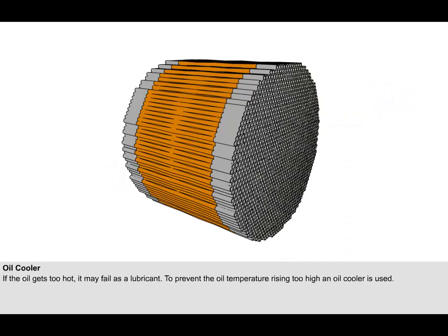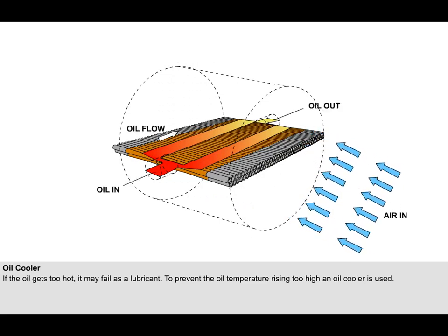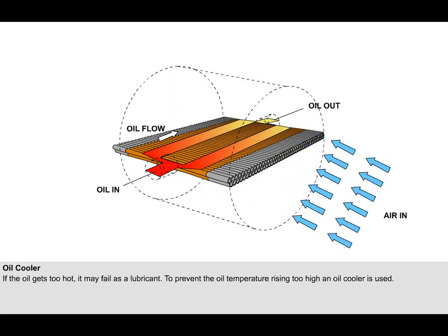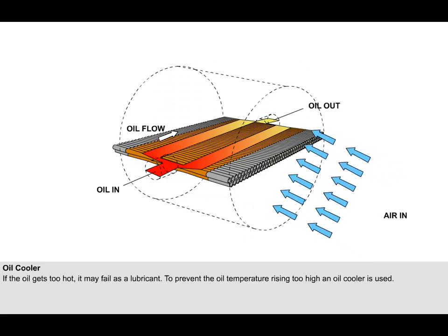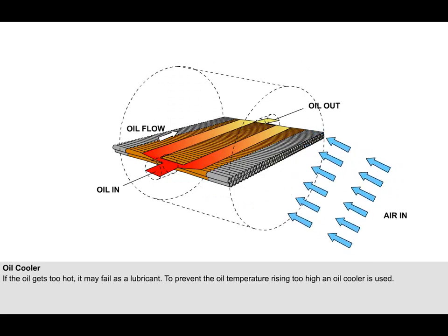In its simplest form, an engine oil cooler is made up as a matrix or tube block, similar to a bunch of drinking straws which have been clamped together. Ram air flows through the inside of the tubes in the block. The oil is allowed to flow between the outer surfaces of the tubes, which are separated by dimples formed in their centre sections. The oil is spread in a thin film which flows through the inner surface of the matrix.